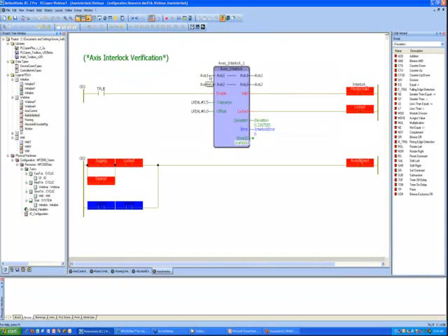It's just sitting right here. I have to specify both of the axes involved with this mechanical setup, and I specify a tolerance that I want to make sure they stay within. In my case, these are degrees, so that's a generous 3.5 degrees. And if there was any actual position offset to account for, the math will handle that if you have some offset that is known. Right now, this output called locked is telling me that those two axes are within 3.5 degrees and neither of them has any alarm.